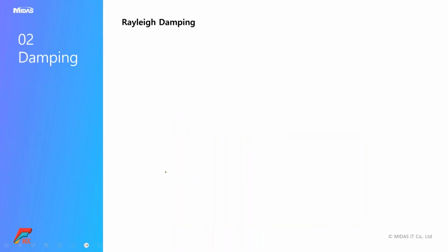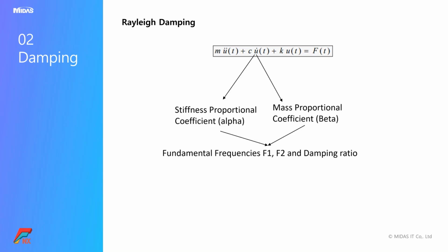So the next thing is damping. In damping, in general, we consider Rayleigh damping. And if you're not interested in Rayleigh damping, you can always go ahead with hysteresis damping, wherein you can create a hysteresis model. You can use a hysteresis model present in the software, and you can provide the hysteresis damping. But Rayleigh damping follows.